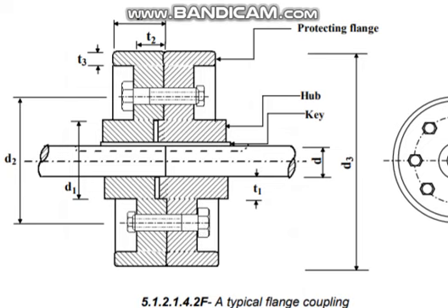You see, actually this is not the side view. If it were a side view, it should have been a big circle. From here to here, people put any kind of drawings. Okay, anyway, see here, this key, here one key is shown throughout it. Normally it won't be like this. One key will be there, and the other side key will be at an angle of 90 degrees.